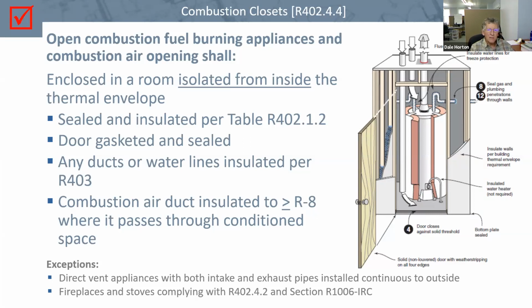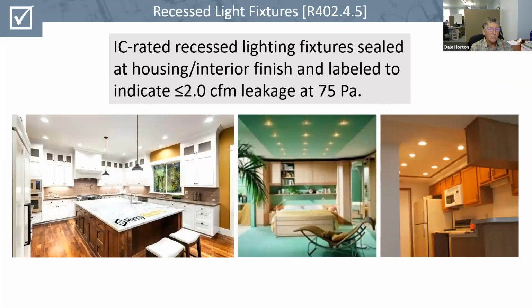And somebody said, well, that doesn't make any sense from an energy point of view. And they said, well, if you really want to have atmospherically combusted appliances, most of the time today that's just the gas water heater, because high efficiency sealed combustion furnaces are so common. Then you'd have to put that atmospherically vented water heater in a closet, insulate the outside of the closet as if it were an exterior wall, and provide fresh air for combustion for that appliance, but you've thermally isolated it from the rest of the building. It's a great idea, but it's probably not going to see the light of day because it will add several $100s to the cost of a building, and be one of those red flag items for builders.